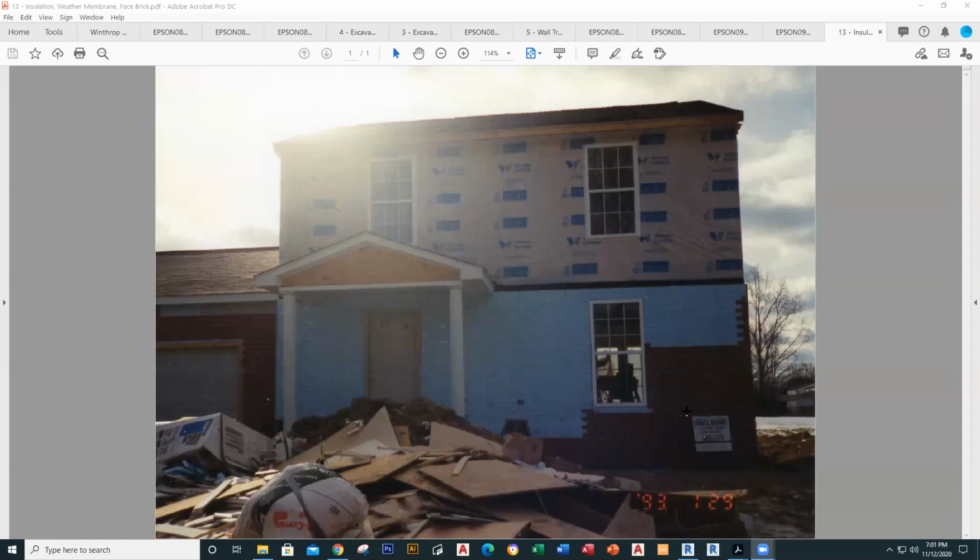Yep. Okay, what's going on there gives you an idea of how it went together. I'd mentioned that there was an exterior veneer of brick, and that's what you're seeing right there. You see that it's got a blue insulation, and you'll see some silver clips on there too. That's how that's done. You have the blue foam insulation, which has grooves in it, and you snap the bricks in there, and there are clips to hold it in as well. So there's a mechanical bond as well.